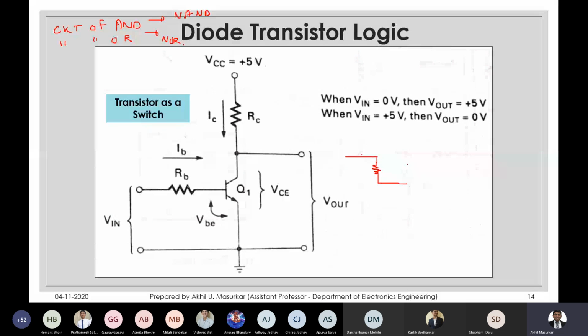So basically this is the AC model of the circuit. I'm sure sir will do this. This is your collector, this is base, and this is emitter, this is RE. The current flowing through this is IB, the current flowing through this is IC, and this is IE. And you can very well check that in a transistor IE is equal to IC plus IB.